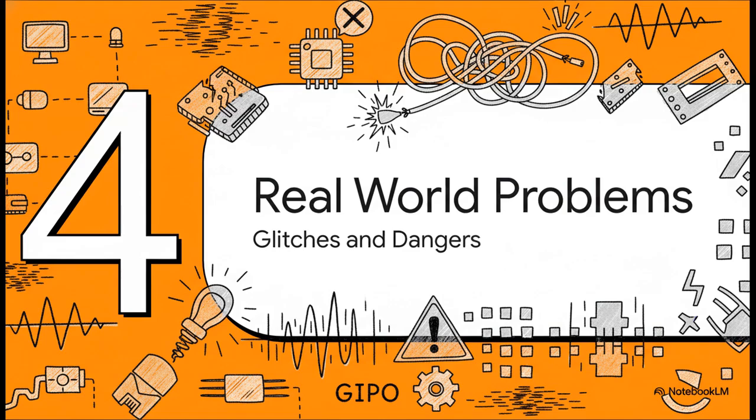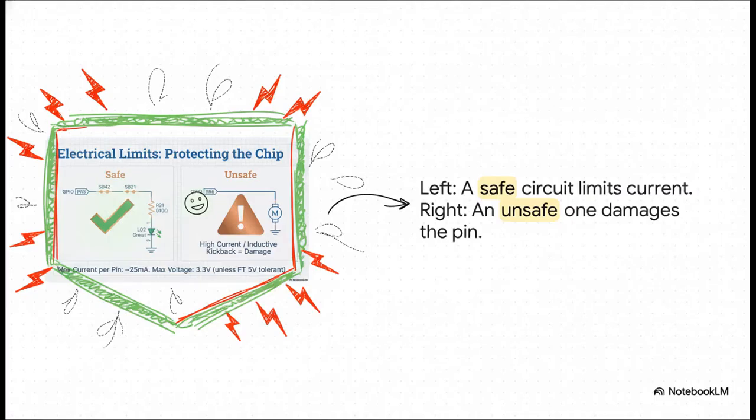All right, so we've got the theory down. That's the clean, perfect version. But the real world, yeah, it's messy. So let's talk about some of the common glitches and real dangers you're going to run into with GPIO. First thing to remember, a GPIO pin is surprisingly delicate. It can only push out a tiny amount of current. We're talking around 25 milliamps, tops.